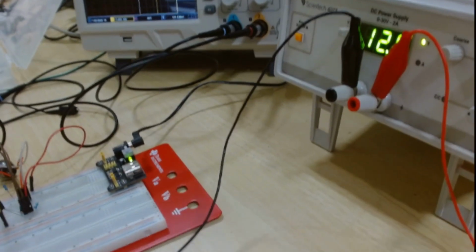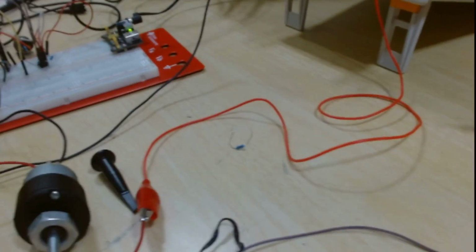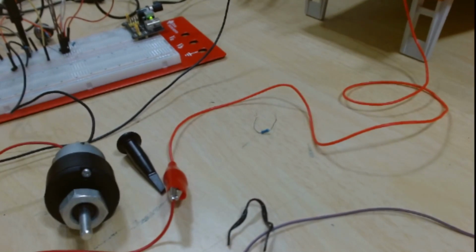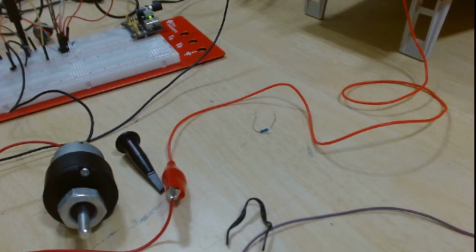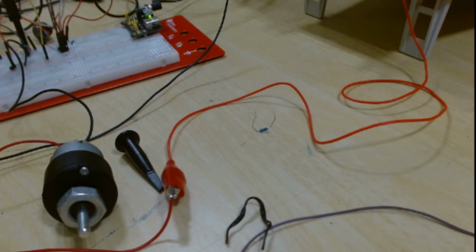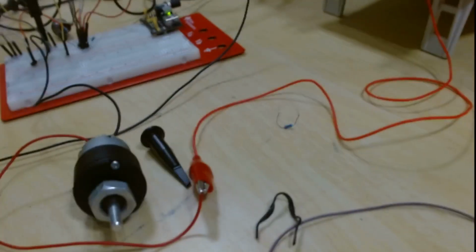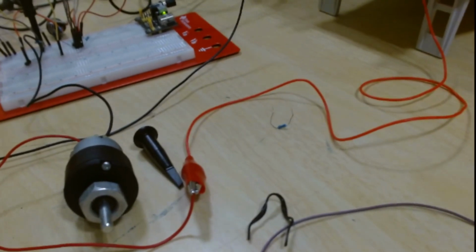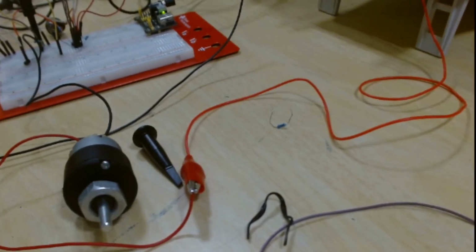Now to generate the necessary current for the motor, I need to give appropriate base current for the transistor. Previously with a 100 ohm resistance, base current was in milliampere. So that is good enough to saturate the transistor. Now when I put a very large value resistor here, base current is not sufficient. Even though the supply voltage is there, you are giving around 5 volts, current is insufficient to turn on the motor. So circuit wise everything is fine.